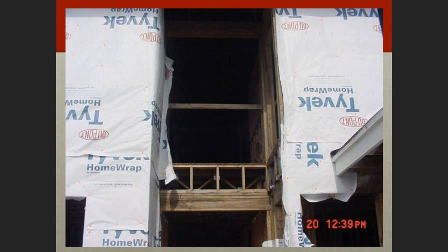In this particular picture, we see that employees have the potential to fall through because we don't have the standard guardrail system. And just to give you a quick recap on the standard guardrail system, the top rail must be 42 inches in height. Then we have that middle rail, or we call it the mid rail. We have a range on that. We usually like to see about 20 to 22 inches there. And then a toe board that's going to be flush with the walking working surface, and usually that's about 4 inches in height, and that goes across the bottom, and that's to prevent overhead fallen objects from striking workers below.